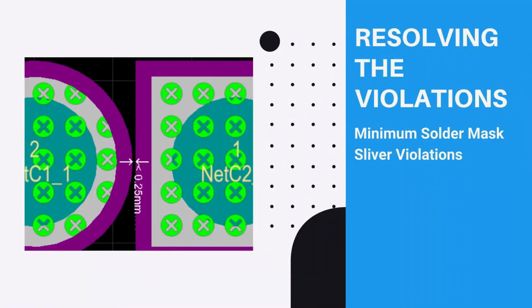For example, if this was a complex multi-layer board for a high-value product, then it is likely that a high-quality solder mask technology will be employed, which would allow a small or zero solder mask expansion. However, a simple double-sided board like the board in this tutorial is more likely to be fabricated as a low-cost product, requiring a low-cost solder mask technology to be used.